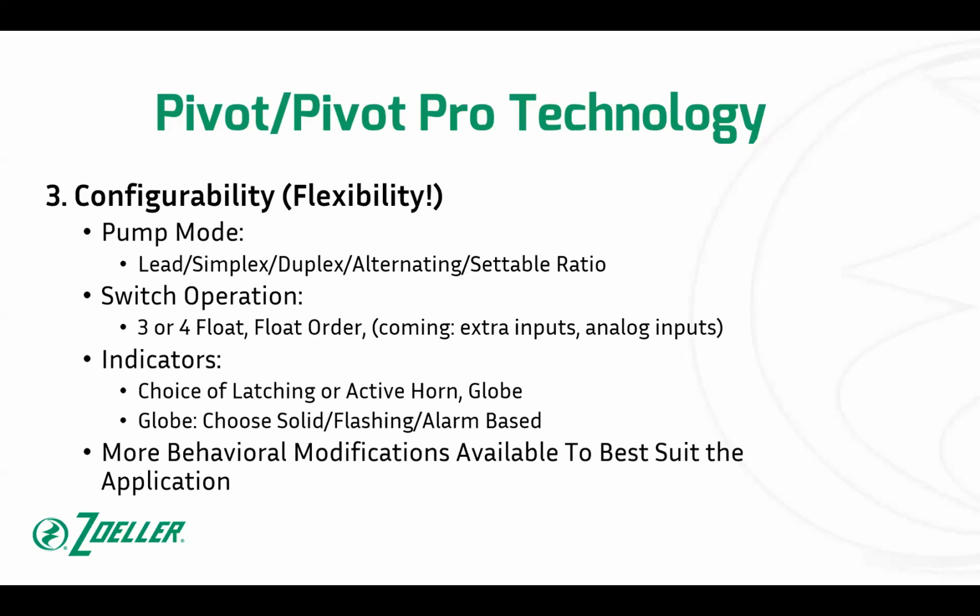You can change whether alarms are latching or active. These are sometimes desired behaviors, but sometimes they're actual requirements based on code. So it no longer has to be the way the panel's built. It now can just be changed. So the panel that you sell to this project is the same panel you sell to this project, because you just change those settings.